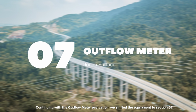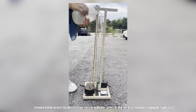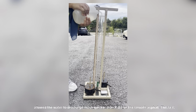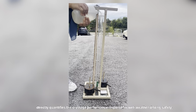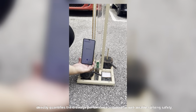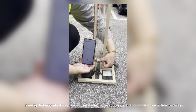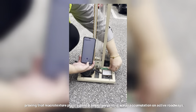Continuing with the outflow meter evaluation, we shifted the equipment to section 07, our rough surface profile. As expected, the higher macro texture and larger surface voids allow the water to discharge much quicker than it did on the smooth asphalt. This test directly quantifies the drainage performance required for wet weather driving safety, proving that macro texture plays a pivotal role in preventing water accumulation on active roadways.